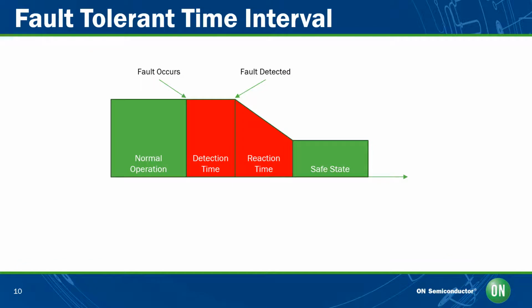Beyond just the ability to detect faults is the latency, or time required to detect and report the fault to the system. In the timeline shown here, the time elapsed between the occurrence of the fault and when it is detected and reported to the system is defined as the detection time. The time that the system takes to react to the fault notification and to place the system into a safe state is defined as reaction time.